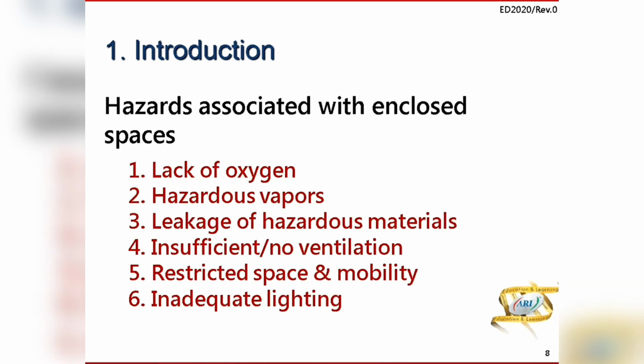So, what are the hazards associated with enclosed space entry? First, oxygen is depleted in this area. Second, hazardous vapors are prevalent there. Third, leakage of hazardous substances, maybe in the cofferdam. Four, insufficient or no ventilation because it's not open. Five, restricted space and mobility. Six, inadequate lighting.